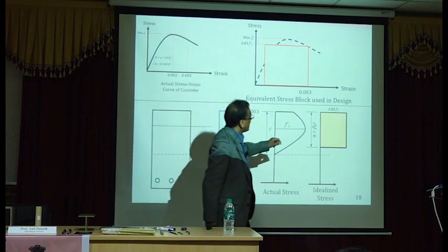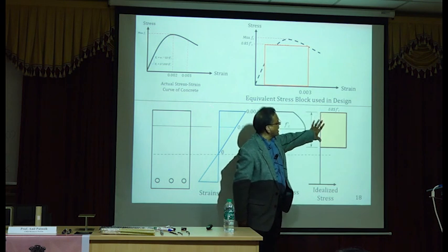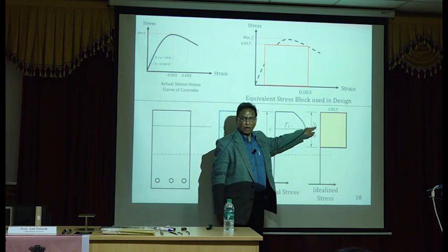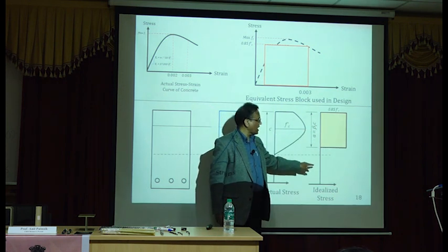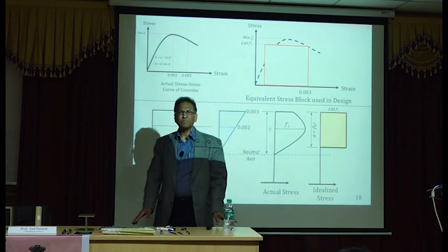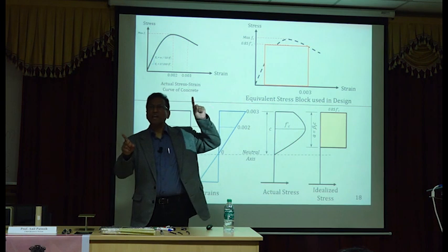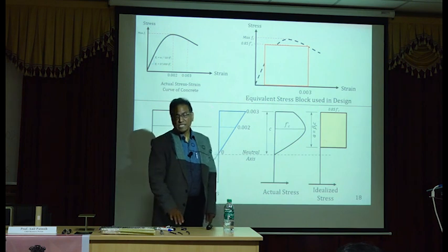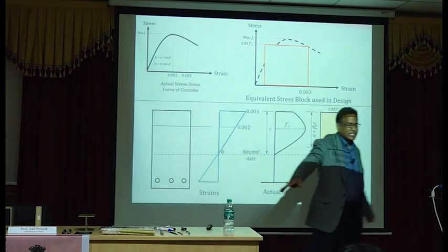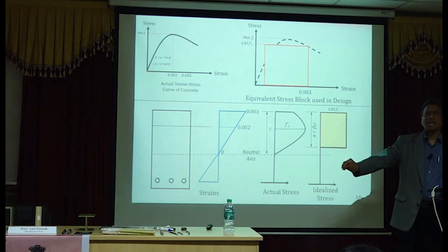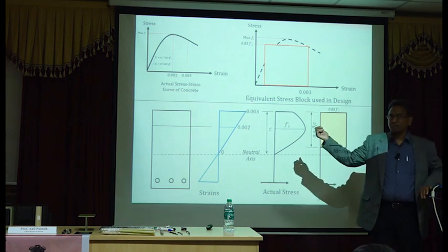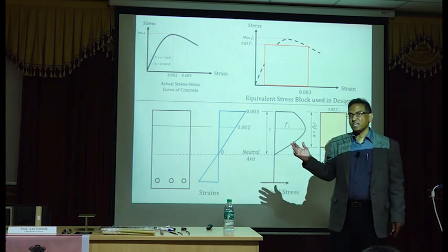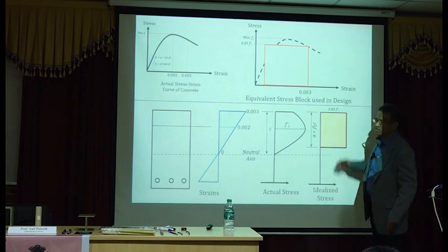Okay? And then also, because this is a smaller depth, my resultant force is also at a higher level, and therefore it should give me a larger moment strength. Does it make sense? Because the moment arm is larger. So that may make a difference. That's the reason you have to be careful not to jump into ACI 440.1 and just use it, then apply the same load factors and call it safe or consistent with IS 456. There will be some difference.